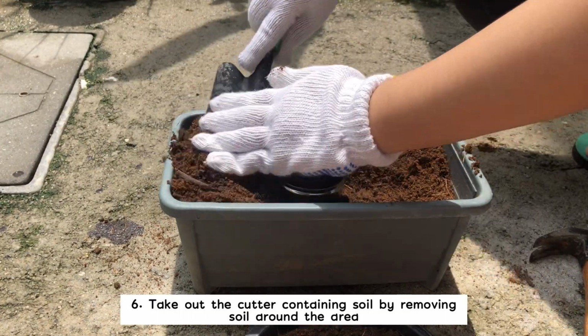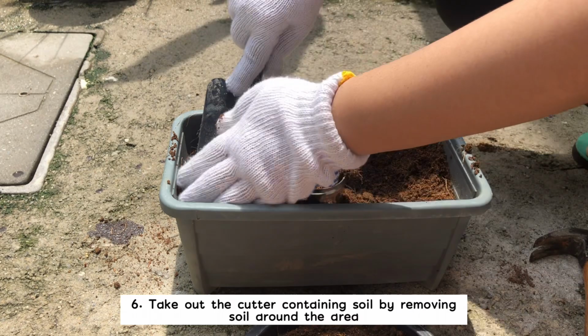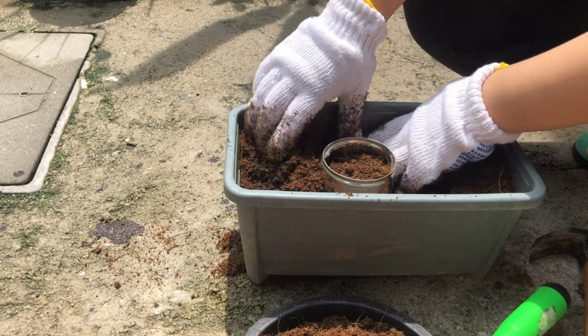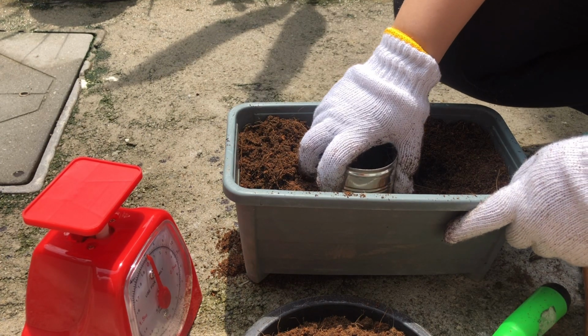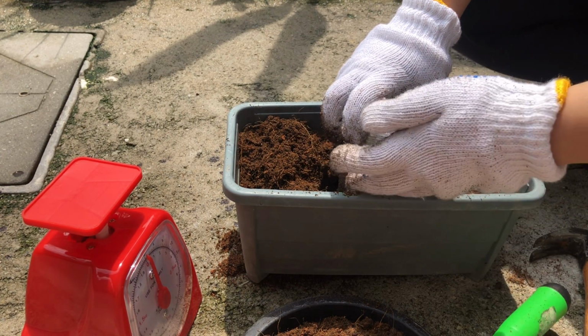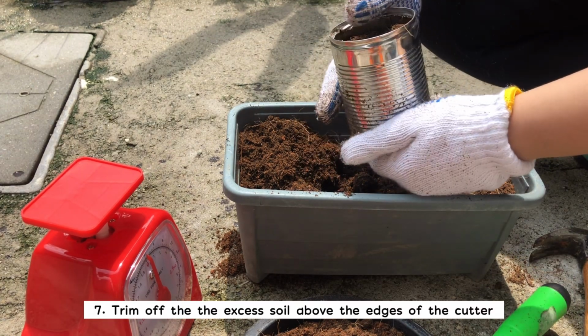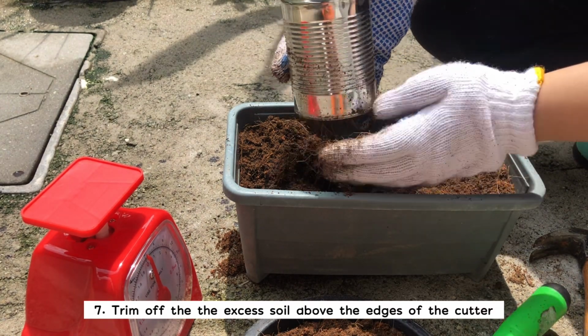For the sixth step, take out the cutter containing soil by removing soil around the area, and then trim off the excess soil above the edges of the cutter.